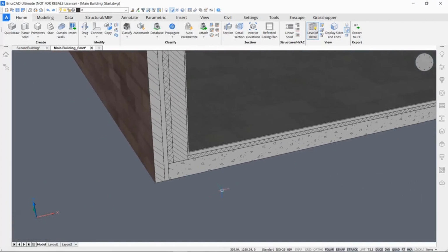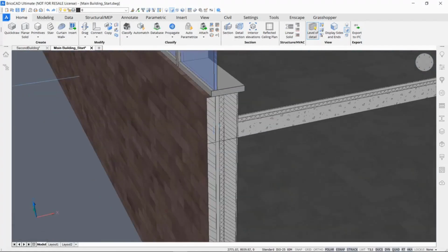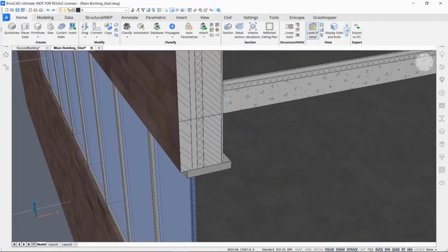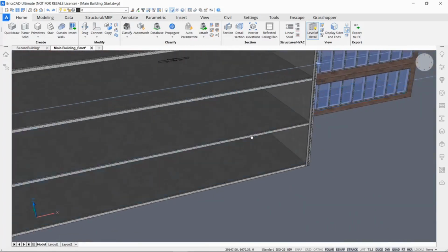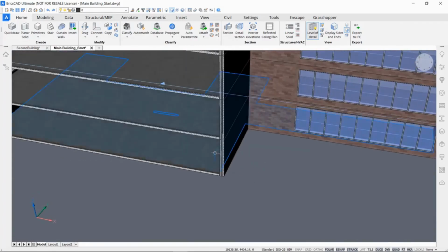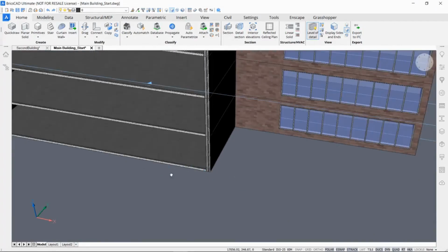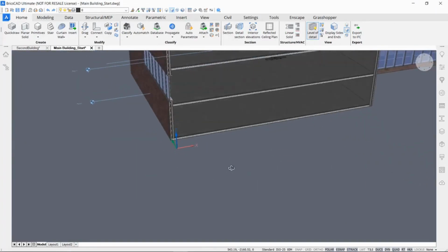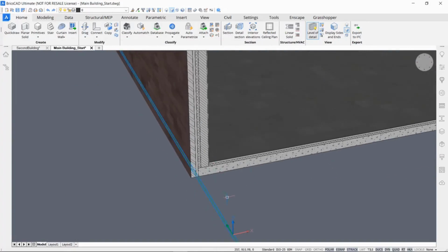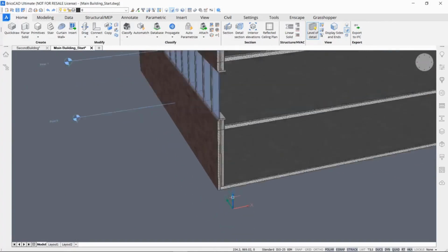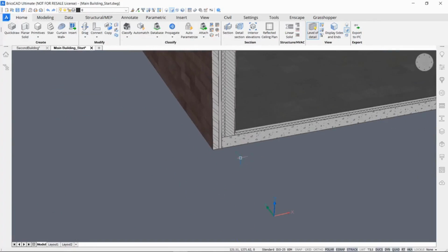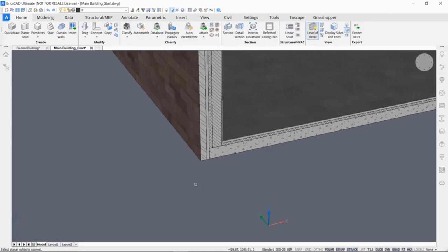Of course, if you see here or like here, these are all wall slab connections with the same kind of situation as the detail we just edited. We actually want this detail all over the rest of the wall slab connections, and we can do that by Propagate. In this case, this is Propagate Planner, and it searches the entire drawing for similar situations so that Propagate can copy this, apply this detail to the other places.